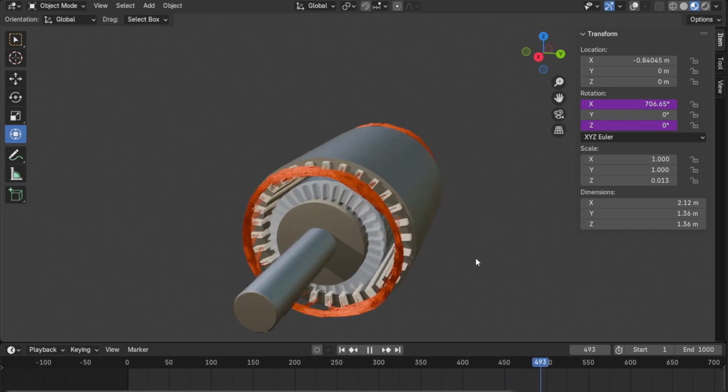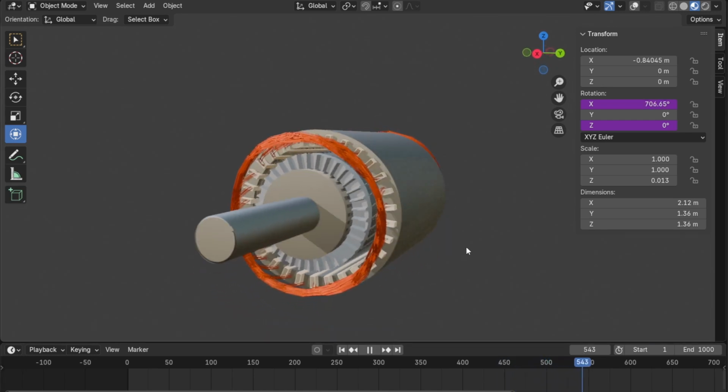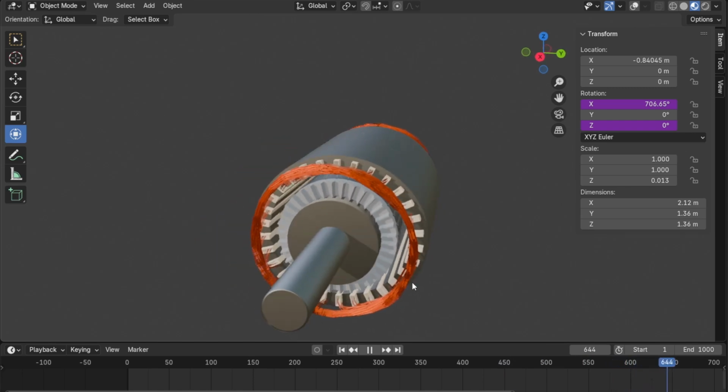Yeah, so now let's think about what happens if we have a bad connection. So, we have our rotor rotating right here. But let's imagine that we have bad connections on all three phases that are equal in severity. Or even better, let's just imagine that the wiring is undersized on the way to this motor. And so we have a voltage drop, right?